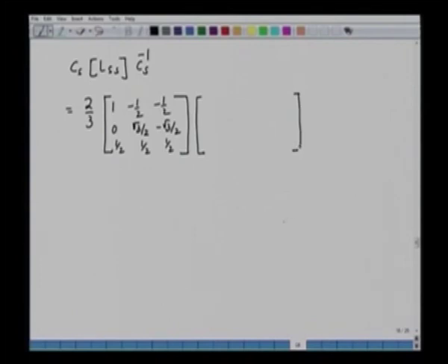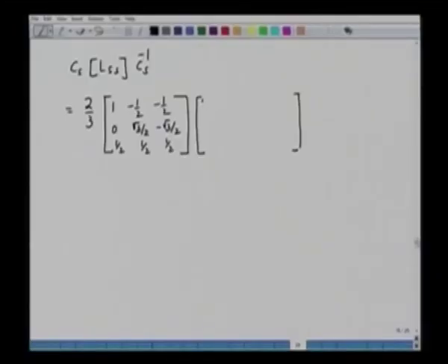If you recall, LSS had diagonal terms which were constants, and it also has the mutual terms. The diagonal terms are LLS plus LMS, LLS plus LMS, LLS plus LMS.